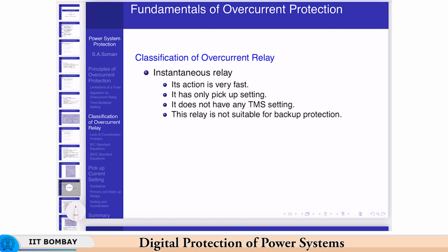It only has a pickup setting. There is no intentional time delay given for an instantaneous relay. So, it has no TMS setting and no time delay.